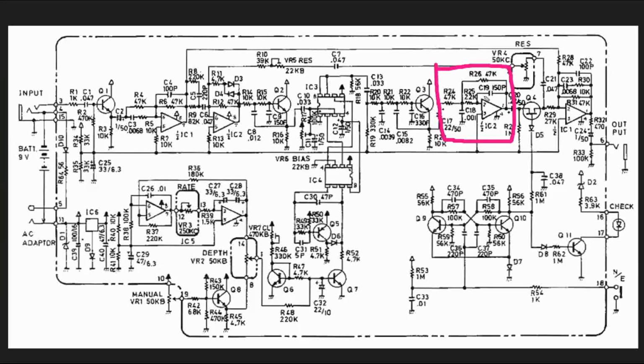Okay, so we're rolling off more of the high frequencies. Why are we rolling off more of the high frequencies? Well, these have two different corner frequencies. And with comb filtering, you can get a very kind of metallic, nasty high end going on if you're not careful. And so this kind of helps with that. Okay, so it's just another filter.